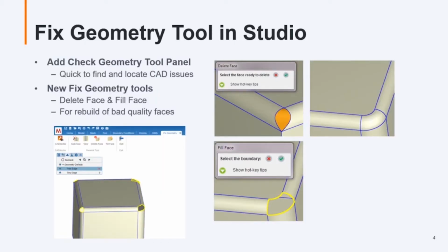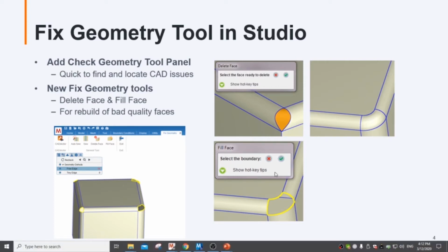Now we have the capability to fix the CAD defects, like we can see in the picture here: auto stitch, delete face, fill face, and I would like to show you how to use it in Studio.